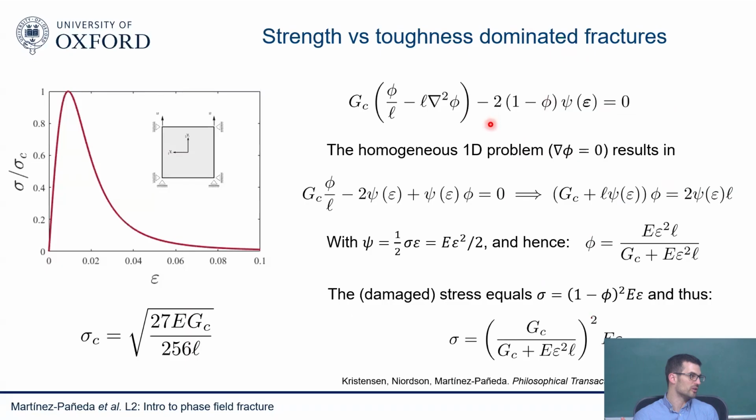This is what engineers normally do before phase field, or they still do, when they are looking only at crack initiation. They will calculate G or K, the stress intensity factor, with a stress analysis, and they will then compare, and that will tell them whether a crack will initiate or not. Here I can model crack initiation and propagation just by having that G idea embedded into the phase field equation. So I don't need to calculate anything. I'm just solving this equation. I'll show you later how to do it.